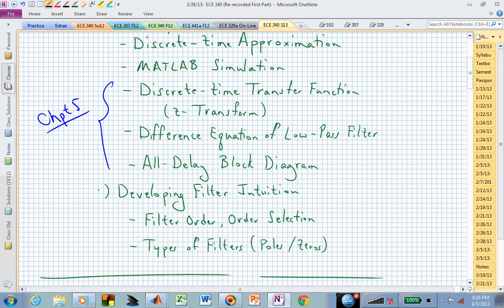That is similar to what we've been sketching with all integrator block diagrams, except now we're in discrete time and we don't have integrator blocks, we have delay blocks, and those may be more intuitive. They just hold the information for one sample period, and then after one sample period they put that value out at the output of the delay block.